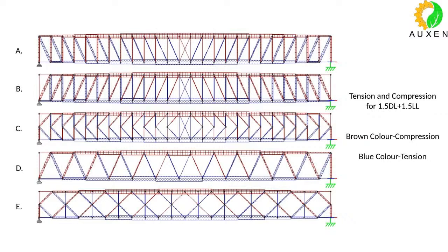In type A, if you look at it, there is tension in the diagonals. All diagonals are in tension. And if you look at type B, all diagonals are in compression. Why is that happening? That is happening because of the shape of this configuration. So if you do not have any chance of load reversal, and let's say there are no wind loads to think of, then only for gravity loads without load reversal, A or B, which will be better? Yes, tell me.